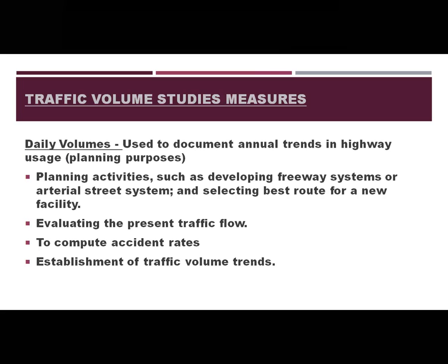It is used in planning activities such as developing freeway systems or arterial street systems and selecting the best route for a new facility. When it is very difficult to move traffic smoothly, we need to provide a new traffic way, but the new traffic way must have a certain volume. That is why we have to do the traffic volume study in both situations.